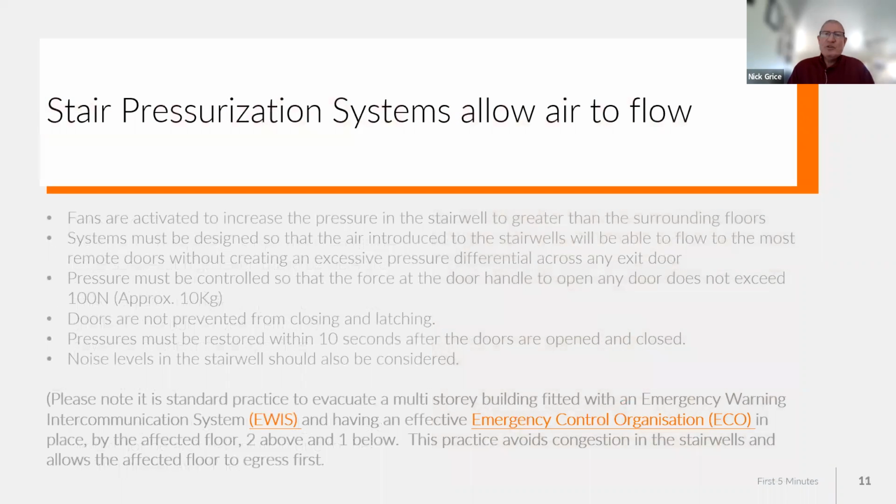So stair pressurization systems, they call them stair pressurization systems because they allow the stair pressure in there to get higher than the surrounding areas. But what they're actually designed to do is to create airflow. So if you open the door, and if anyone has been in a building and they try and open the door when a fire alarm's gone off or when you're doing a trial evacuation, and it's quite hard to open into a stairwell, that's because of the fans that go in there.